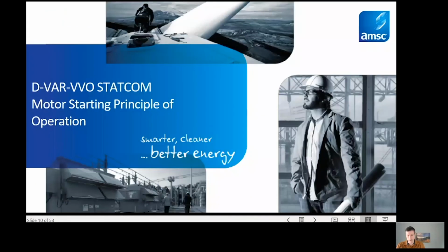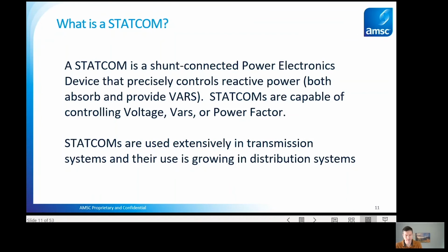So now I'm going to go through and introduce a StatCom technology and why it's a nice fit to solve this motor starting reactive VAR problem. So a StatCom, very simply, is an inverter, a power electronics inverter, that is optimized to just process reactive power.